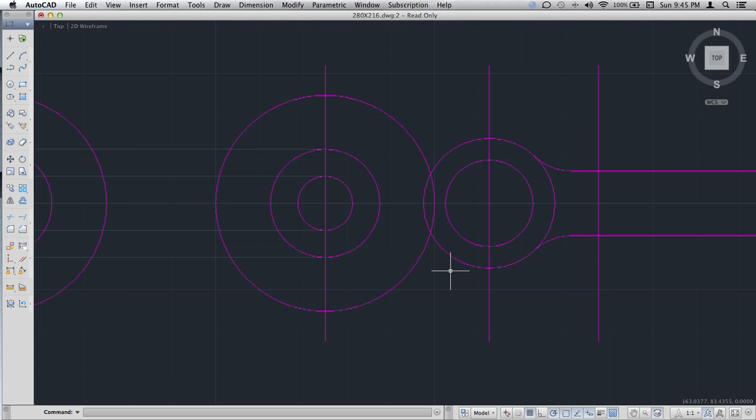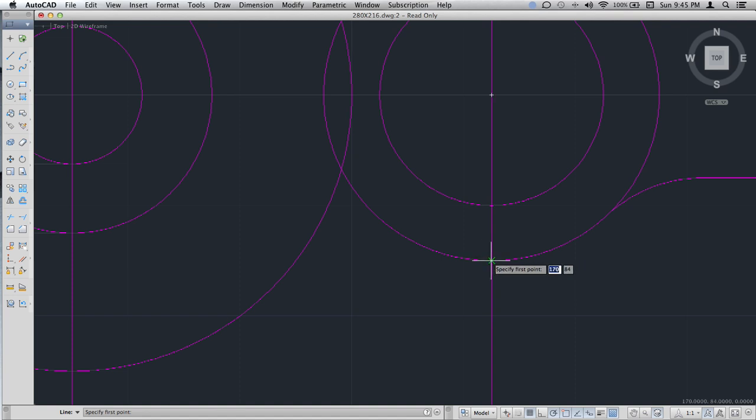And we want to do intersection point. Come over here. Make sure it's 0 or 180. It's just flat, the line here. That's the only problem with the object snap. If you have too many selected, it's going to key off on too many things, and you run the risk of causing problems for yourself.